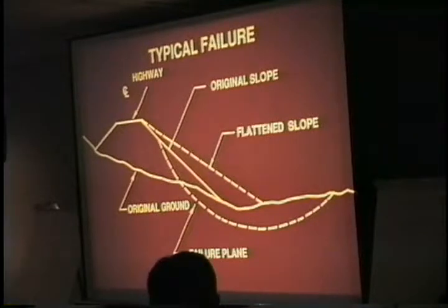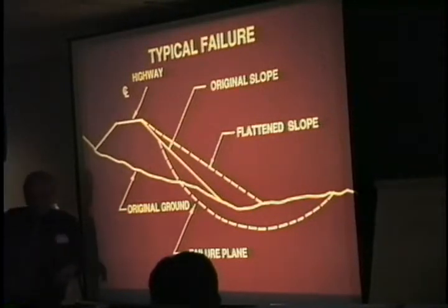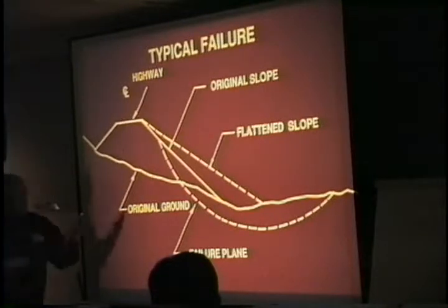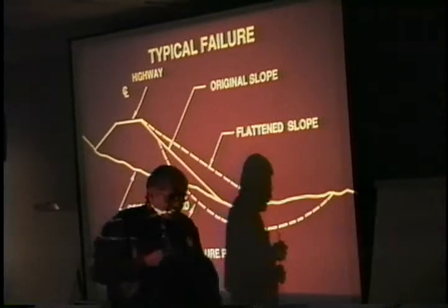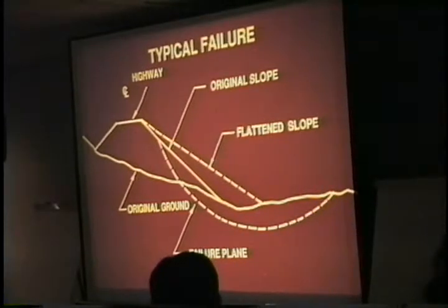Maintenance people are already noticing some cracks in the slope, and a little bit of differential settlement taking place here. And so the maintenance guy says, well, why don't we go ahead and flatten the slope on this one? Flattening the slope corrected the failure that we had last year. So let's flatten the slope here. Now, is flattening the slope here going to correct that problem?